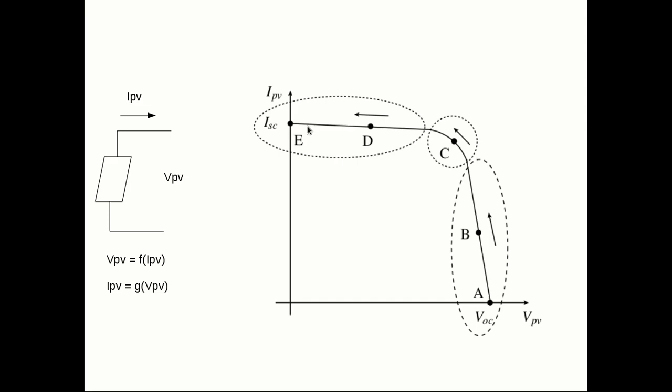As you can see, this has a very high slope. Here the slope is very high with the current. So the voltage is high, but the current is rapidly changing. And it is this zone here which is of importance. Here the slope is what you could say nominal. But most importantly, this is where you get the maximum power from the solar panel, particularly this point C.